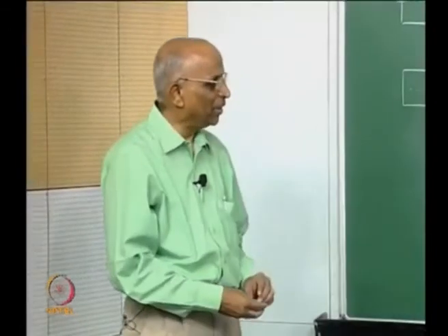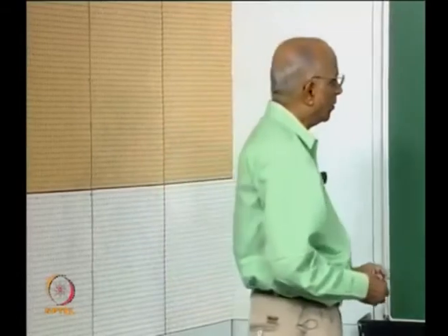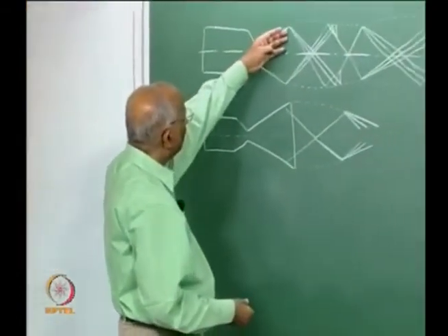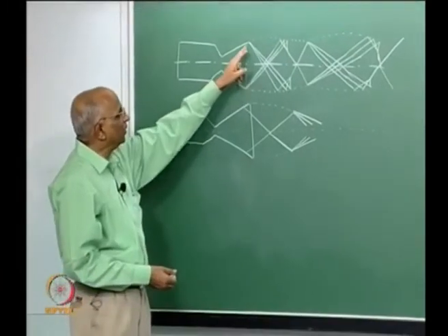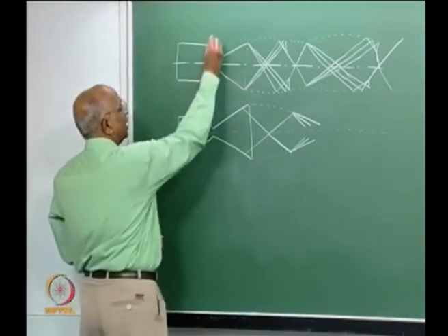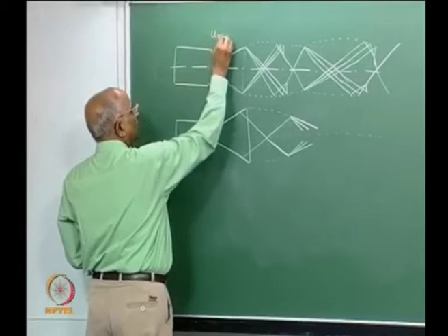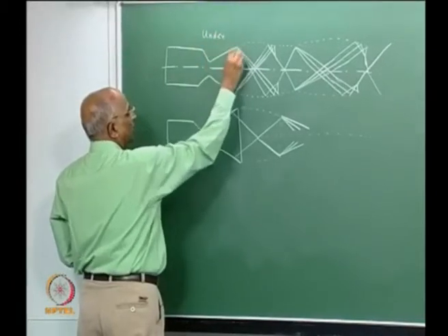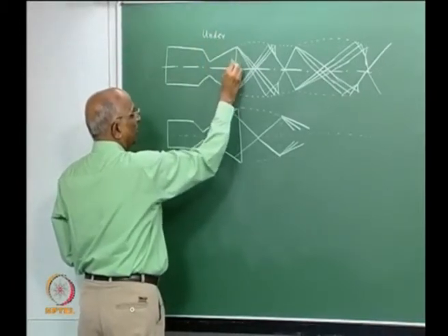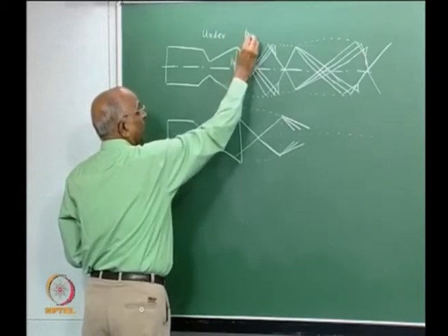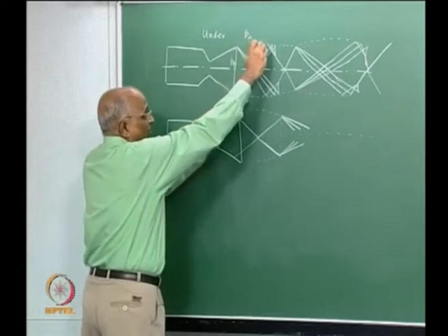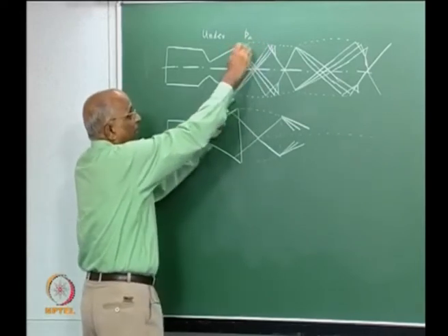Good morning. We will continue with what we were doing with nozzle area ratio. I replotted the figure which we had in the last class. We had one case, the under expanded nozzle. In other words, the exit pressure here was higher than the ambient pressure, so that the flow continues to expand. How does the flow expand when it meets the outer?